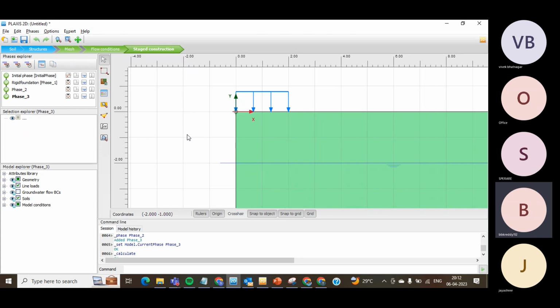Is it possible? See, when you are changing the base structure, anything is possible. But when you are changing the base structure, it is a must that you remesh the model. Because the software first, you told it is a 15 noded element. Now again, you are asking to do it as a 6 noded element. So it has to redo that particular mesh part. But the remaining things, you don't want to change anything.